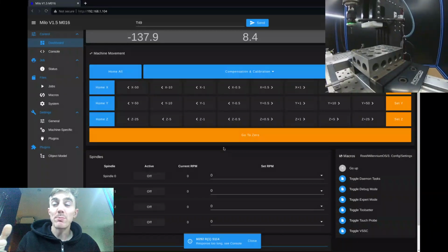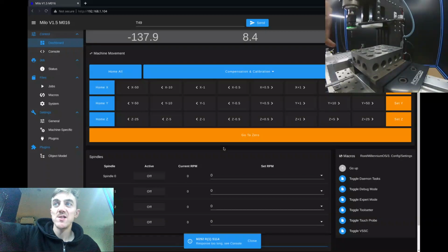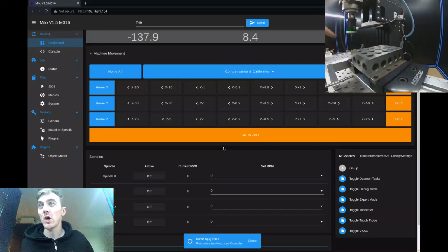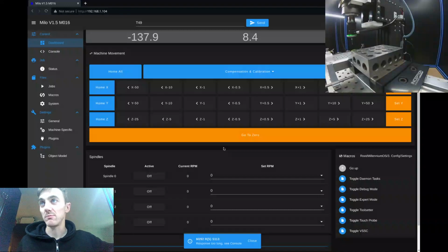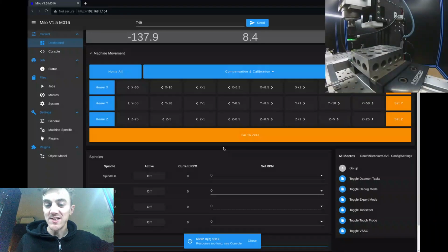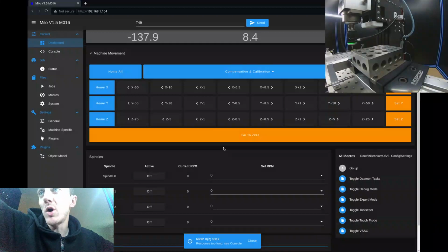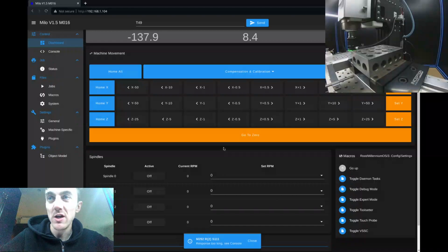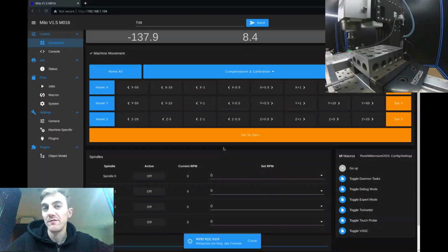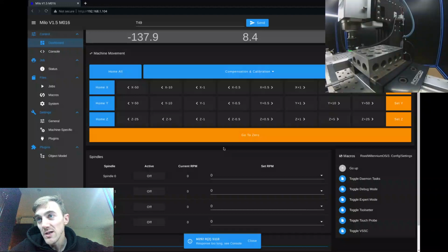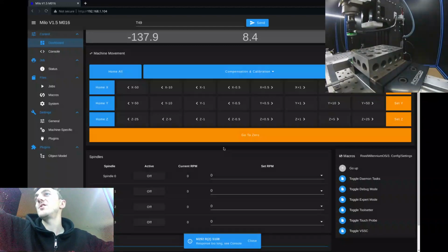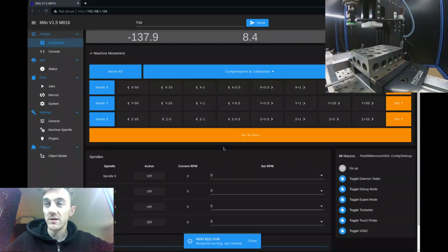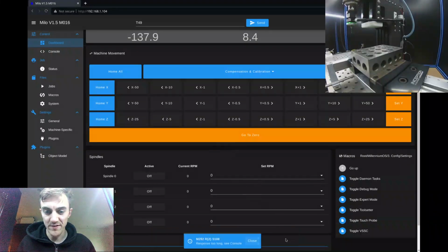So now we're probing the reference surface, and the reference surface is this fixture plate down here, and that has a known distance to our tool setter location, and that is the same thing as setting the tool length for our probe, our datum tool. It essentially allows us to measure accurate Z heights for tools. So you can see this is running twice, 3 times, and backing off, and now we have an accurate position of the datum surface, of the reference surface.